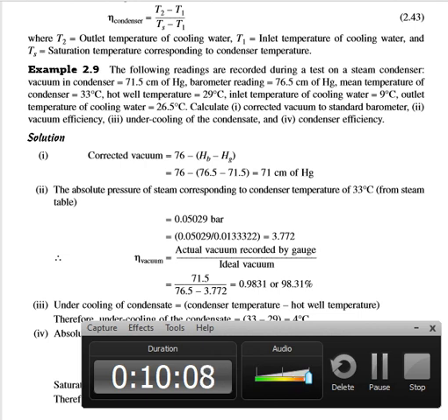First of all, you have to open the steam table. From the steam table, you have to find the value for temperature 33 degrees Celsius, and from 33 degrees Celsius we are getting the 0.05029 bar pressure. And this pressure I have converted into mm of Hg, because all numericals are converted in the form of mm of Hg.